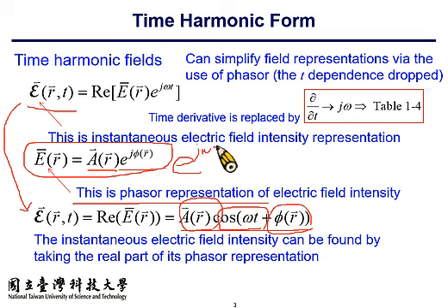But you know that, I know that, so let's agree that the so-called phasor representation has the time dependence exponential j omega t. So we don't have to write it every time, okay? The beauty of the phasor representation is we don't write explicitly the time dependence. The exponential j omega t doesn't have to show in the phasor form.